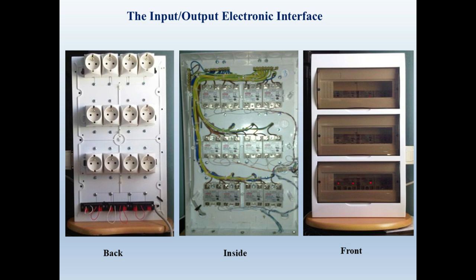The interface has 12 AC output sockets where the devices to be controlled can be connected. The interface is also connected to the AC power supply to provide power to the devices to be controlled. The interface also has 5 inputs where dry contact on/off alarm switch can be connected to provide for alarm events occurred in the system to the mobile user.